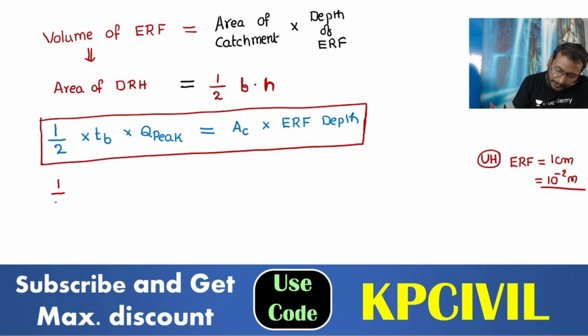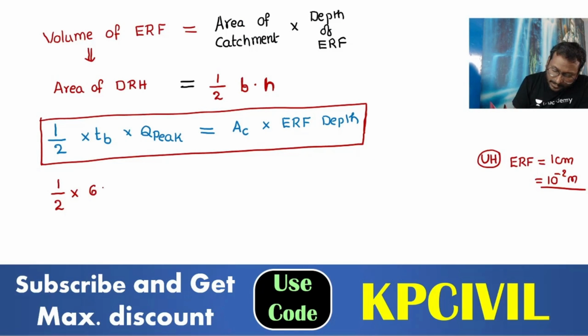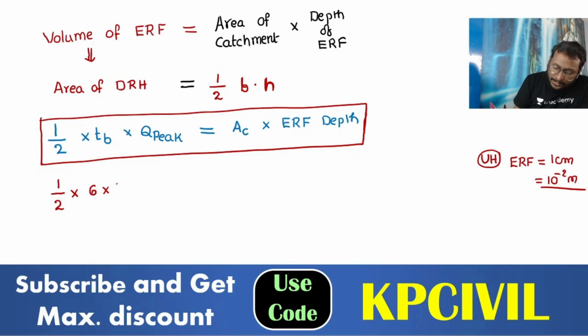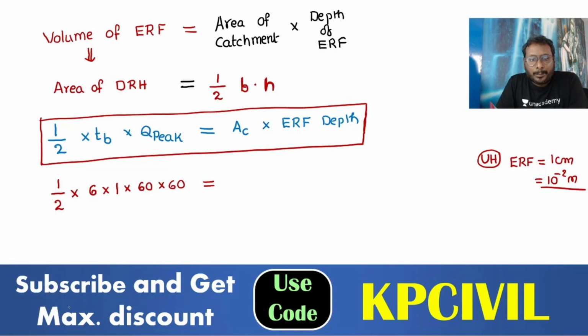So from the given diagram, half into, what is the time? Time base 6 hours. Peak discharge 1 meter cube per second. I am converting seconds to hours: 1 meter cube per second is 60 into 60 meter cube per hour. So half into 6 time base, into 1 peak discharge, into 60 into 60 to convert meter cube per second to meter cube per hour.